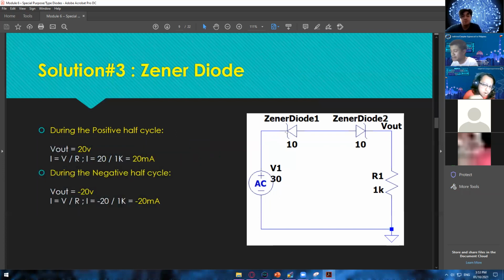Once it passes through this one, it will deduct 10, and then it became 20 now at this point. And then at this point, it's now in a forward bias connection during the positive half cycle. So that is why the reading on the V out is 20 volts. The same with the negative half cycle. The first one is in forward bias, but after passing to the second one, it's now in reverse bias.